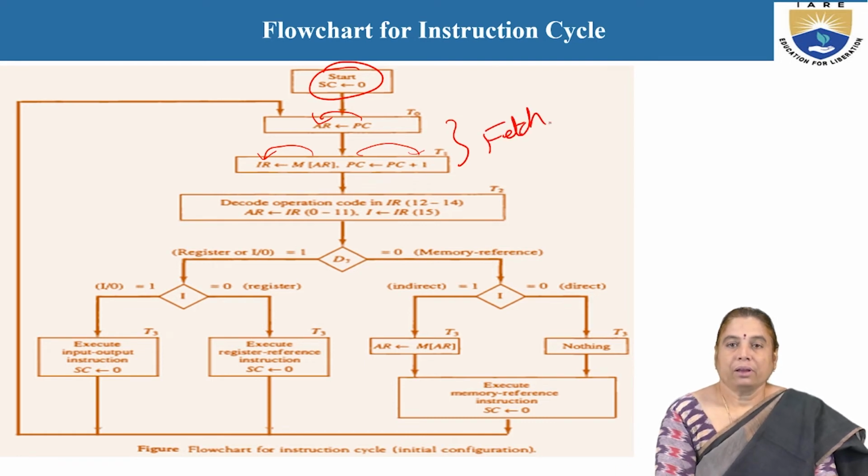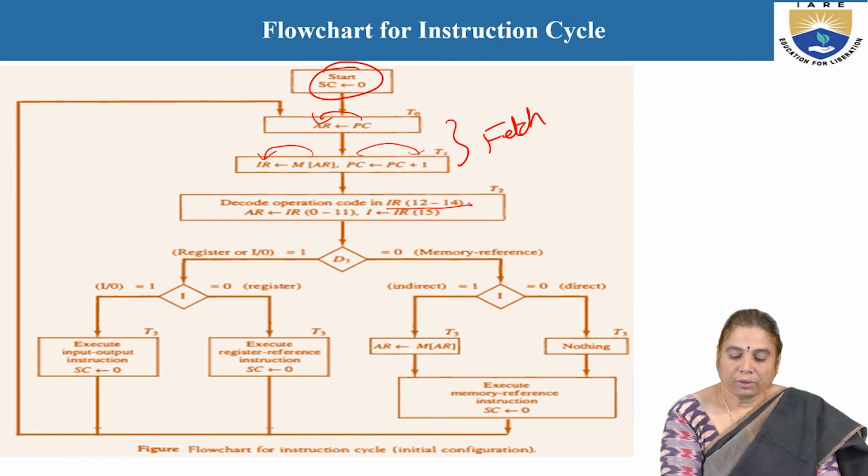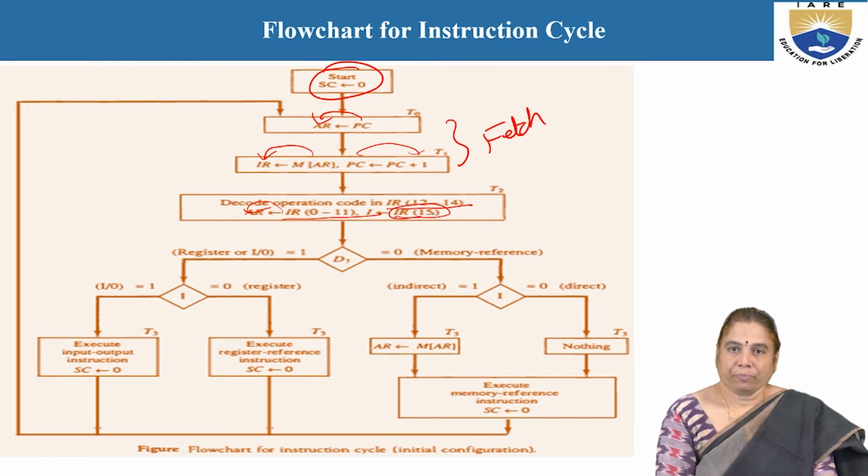After fetching, the decode operation is performed. During decode, the instruction is represented in the instruction format. So IR bits 12 to 14 are the opcode. Bits 0 to 11 are stored in the address register. IR bit 15 is the I value.